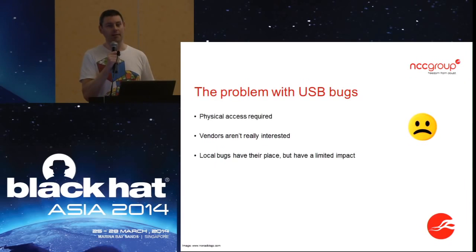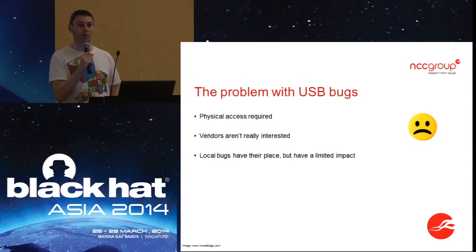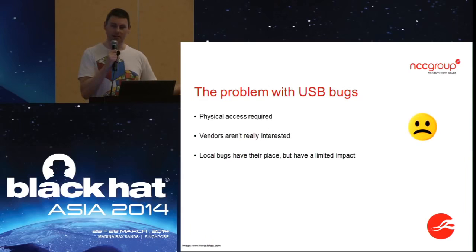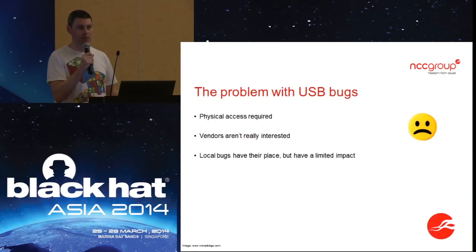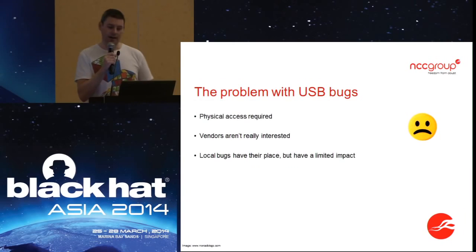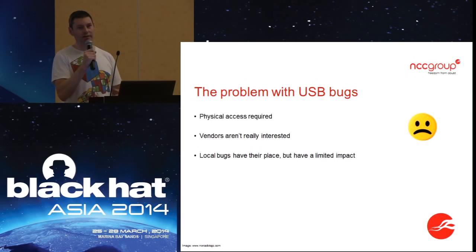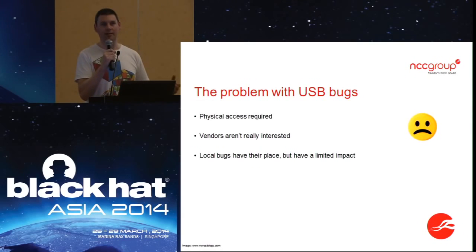When you plug in any USB device, the host that you're connected to doesn't know anything about that device, and it has to go through this phase called enumeration, which is a kind of question and answer session between the host and the device to try and find out what type of device class it is. Is it a mass storage device? Is it a printer? Is it a camera? That kind of thing. Then, what speed does it want to run at? What kind of capabilities does it have? And also, what kind of protocols does it want to talk once the driver has been loaded by the host OS? During that whole phase of communication, there's a hell of a lot of data that's exchanged between the host and the device, and the device and the host.